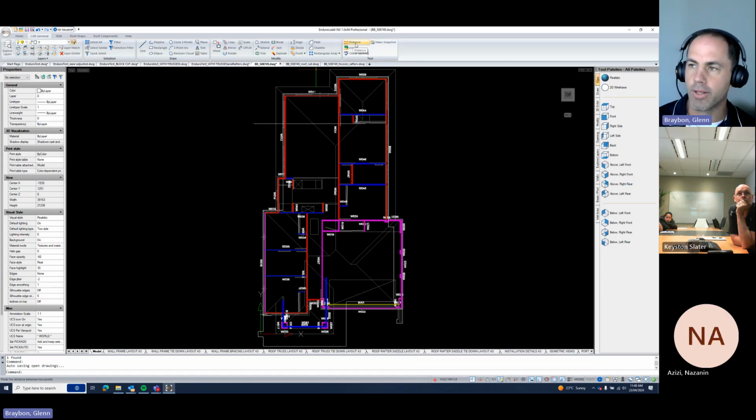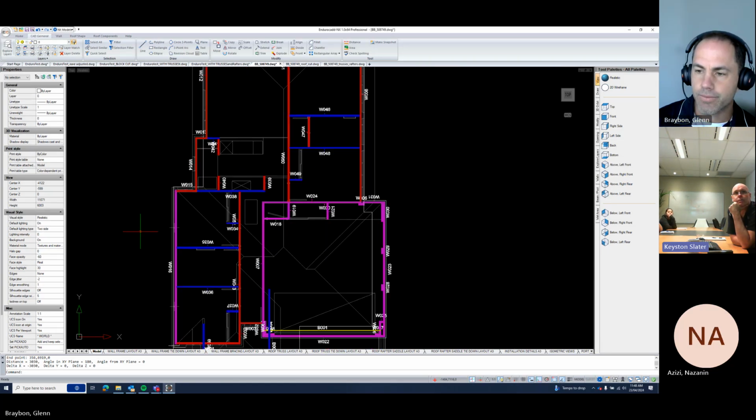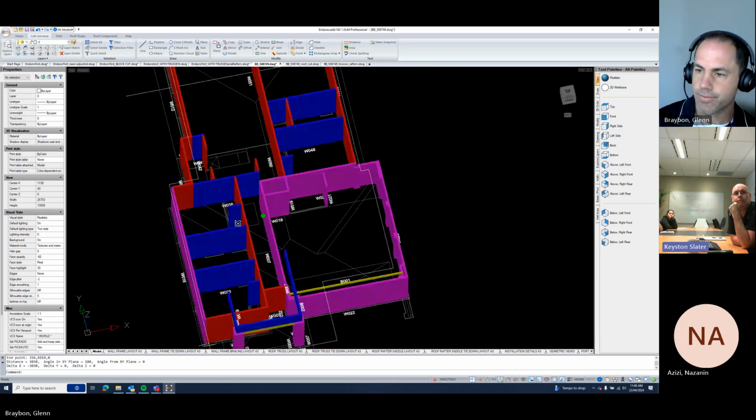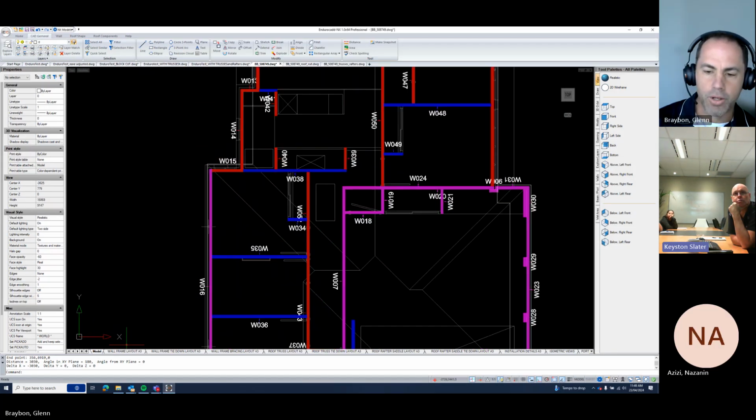I think you'll probably use distance. If you type in DIST, it gives you a measurement between two spaces. You can see down here 3030 is our X dimension. So if you're looking in plan view and the two walls are say different heights, that still works on the horizontal plane here, the screen space. Correct, because we're clicking on two points.